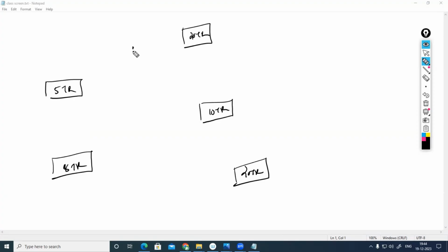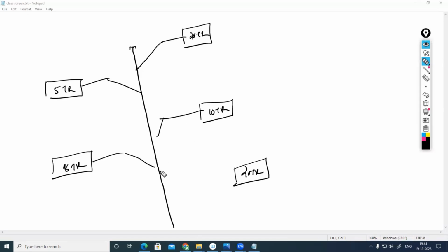So I will be having a common drain pipe. This pipe will be going above the false ceiling. And from all the machines, the condensate drain pipe I will be connecting there. Okay. Routing and all we can study in the plumbing class. Okay. So the slope will be this side.